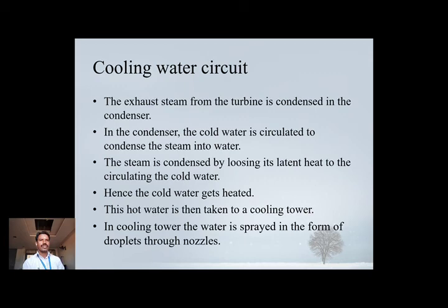The exhaust steam from the turbine is condensed in the condenser. The condenser always carries the heat. Steam is condensed by losing its latent heat to the circulating cooling water. That is the main purpose of the condenser. In the condenser, the cold water gets heated, and the hot water is taken to the cooling tower.